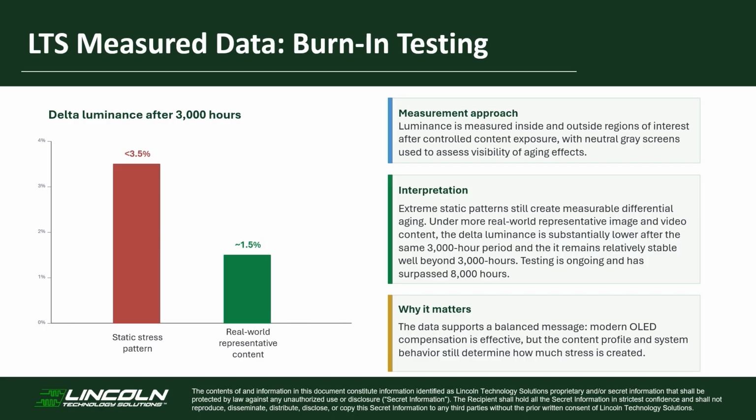The measurement process compares luminance inside and outside defined regions of interest using neutral gray screens to make aging-related differences easier to detect. Extreme static patterns still produce measurable differential aging. Real-world representative content produces substantially less variation. Ongoing LTS testing has now continued beyond 8,000 operating hours.